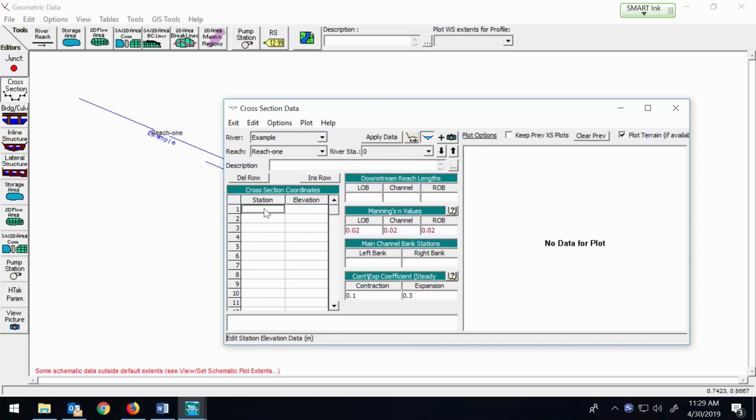So this top left edge, 0, 4, bottom left, 0, 0, bottom right, 7, 0, and 7, 4. All right. We'll enter in downstream. Actually, I'm not even sure if you have to, because we're not doing anything downstream of this particular section. Remember that this section is going to be at our control point. So I'm just going to experiment with leaving this blank because there isn't going to be anything downstream.